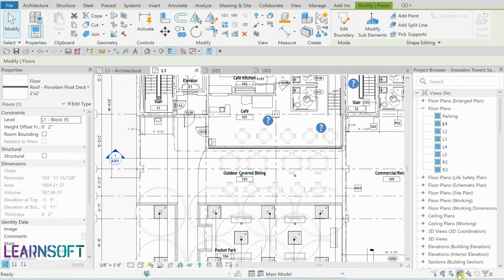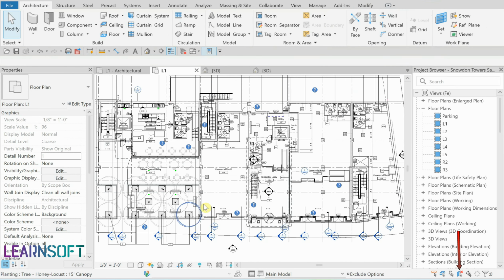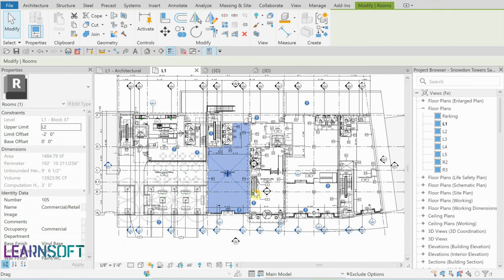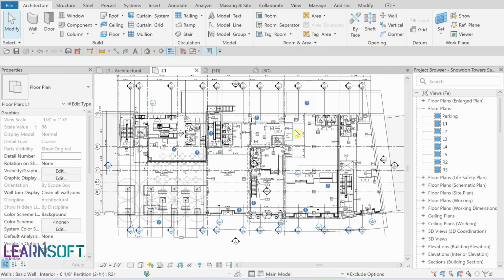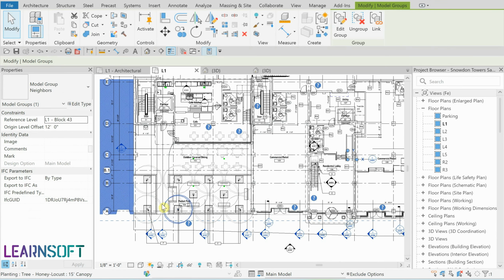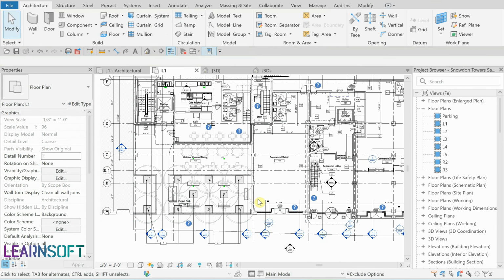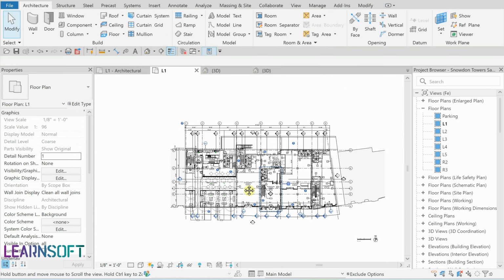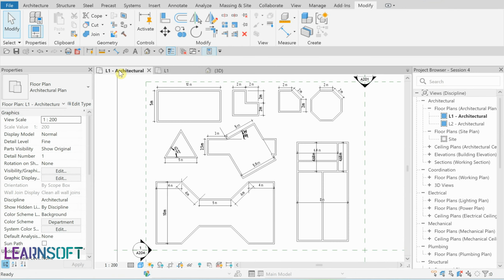When you deactivate selecting faces, then faces like a floor cannot be selected anymore, and you cannot work with surfaces anymore. In this condition, you can work on walls and families instead. Let's shift to Simple Plan.